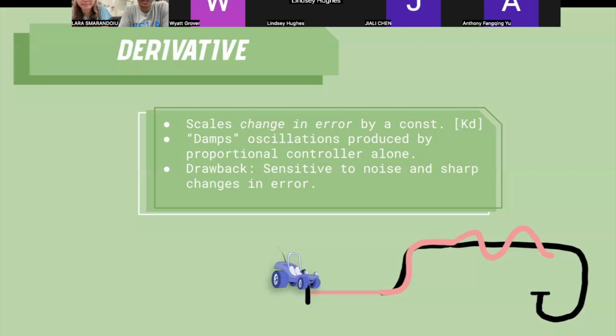That's right. One way that you can actually think about how you might go about smoothing this kind of error is by keeping track of not just the last measurement. Again, to make this concrete, let's say that the way that you actually keep track of your error is that you know exactly how far your car is away from the track at all times. 1 second it's on the track, next second it's 1 inch to the right, etc. So instead of just keeping track of the last measurement, you keep track of the last few and then take an average.